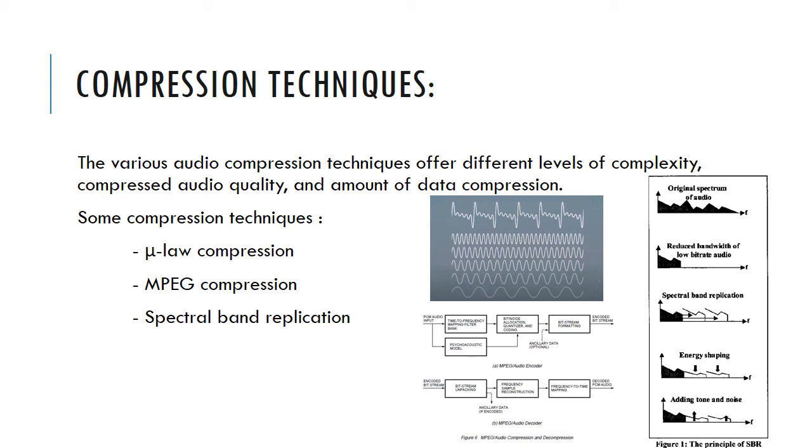The codec itself transmits the lower and mid frequencies of the spectrum, while SBR replicates higher frequency content by transposing harmonics from the lower and mid frequency at the decoder. Some guidance information for reconstruction of the high frequency spectral envelope is transmitted as side information.